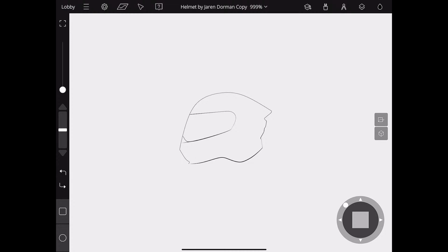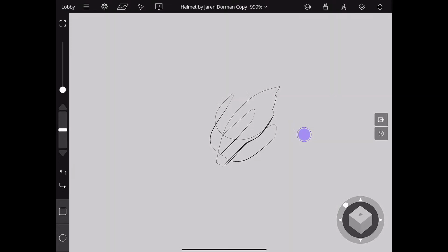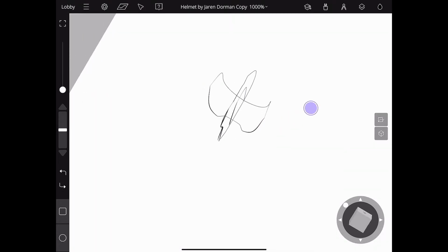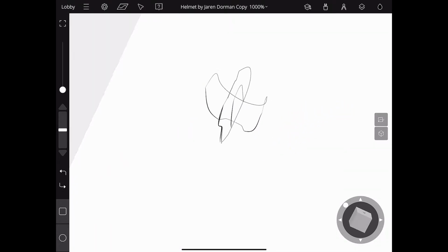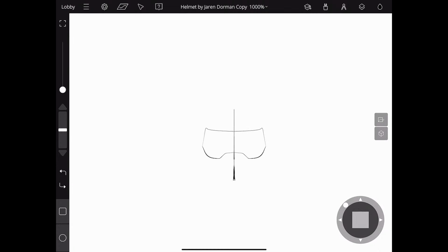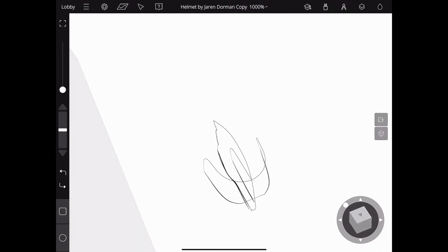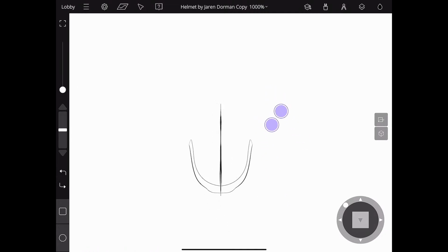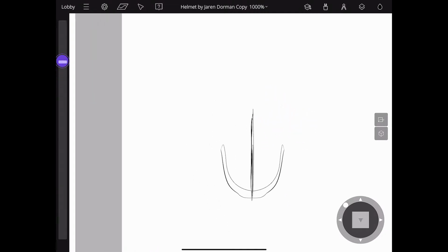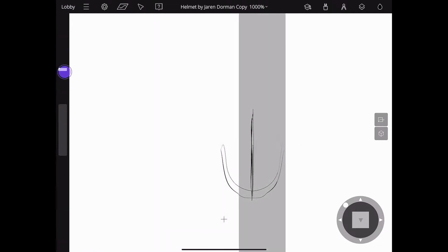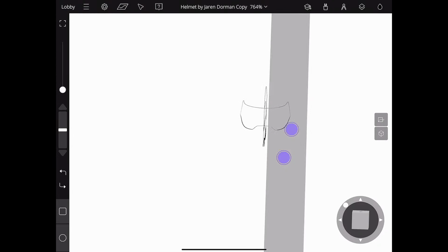So anyway, we have this side sketch, and then I immediately started pulling it out in 3D. What that means is the plane is not quite in the center, so I'm going to move that, and this is great to learn. We want to go to the top view and move our plane a little more center in view, just so we can see it better.